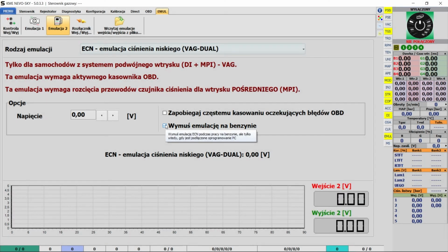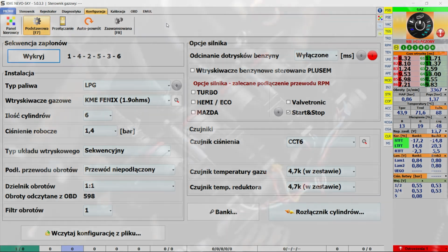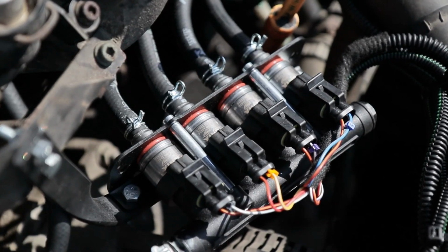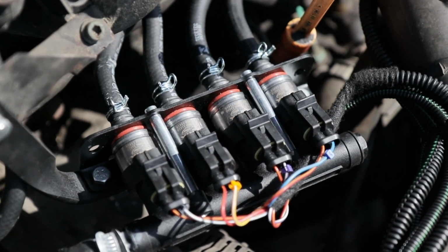Remember, in some cars the cylinder breaker may not cause an OBD error, even after prolonged operation with the cylinder switched off, e.g. cars from the Renault-Nissan Dacia group. In this case, check the connection manually by disconnecting the gasoline injector circuit. To confirm, you can use unplugging the ignition coil plugs.